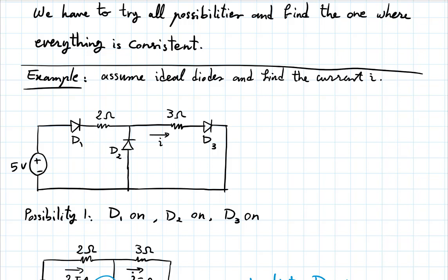You can even extend it further. You can look up the characteristics of a diode from a data sheet from a company that sells you a diode, and they'll give you a graph. And you can just select points on that graph and put them in a lookup table, and use that in your code to solve for the whole system of equations. Those things are all doable, and in fact, they are done.